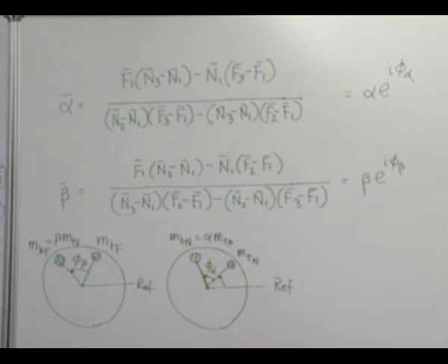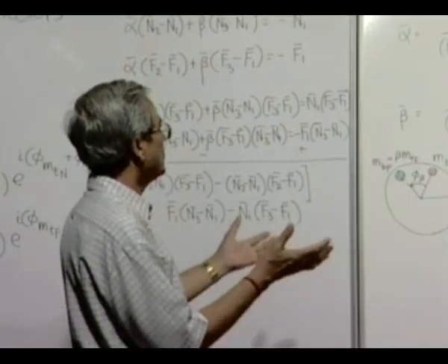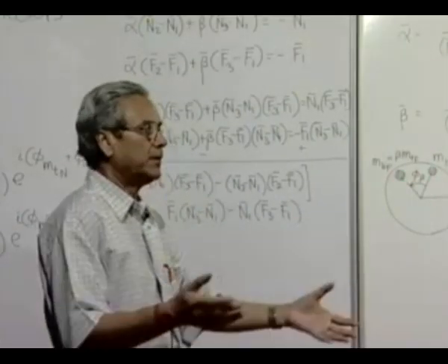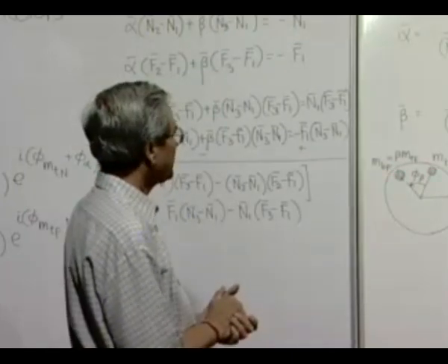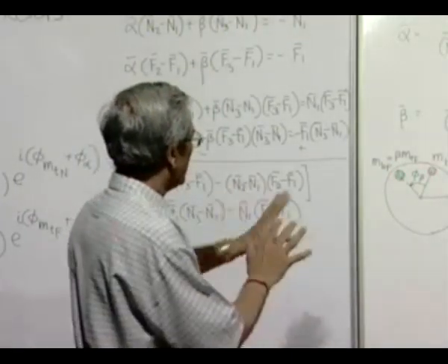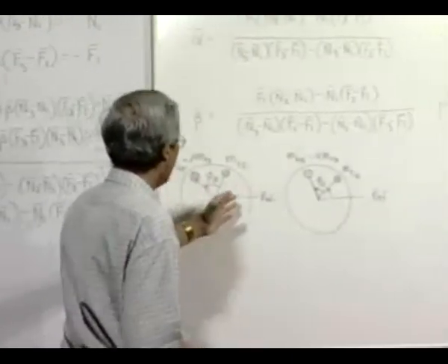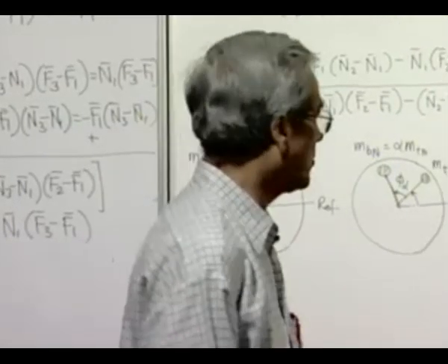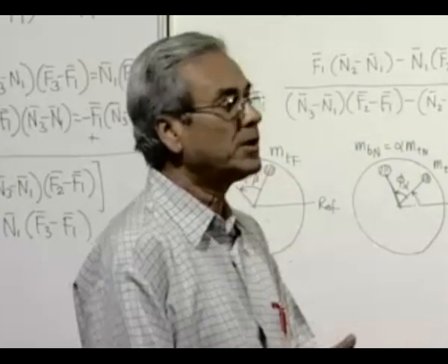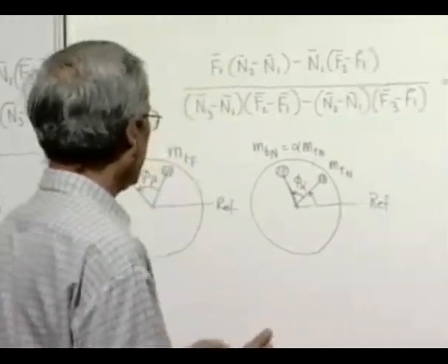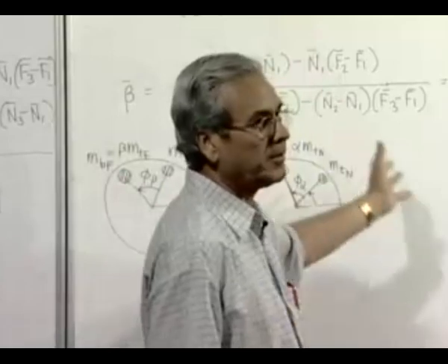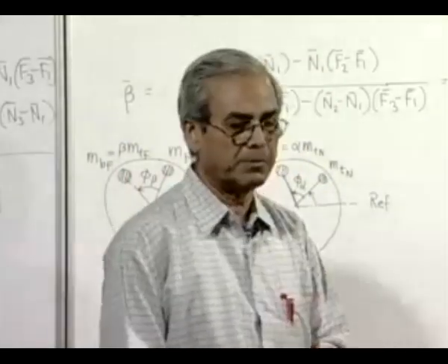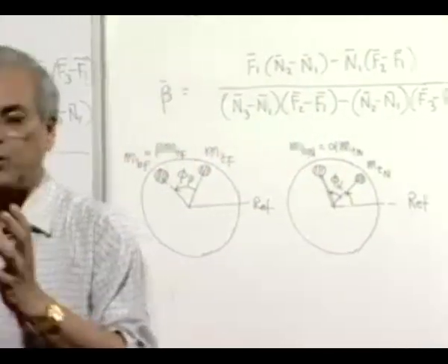So, therefore, you can see that even if a rotor is too big, it is not necessary to bring it to a machine, and it can be balanced in its own location. Now, this particular method which I have shown, where we have used a sine wave generator, vibration pickup and a double beam oscilloscope, as we mentioned in the case of disc like objects, here also you can solve the problem of field balancing using only a vibration meter, which will give you the amplitude of vibration.